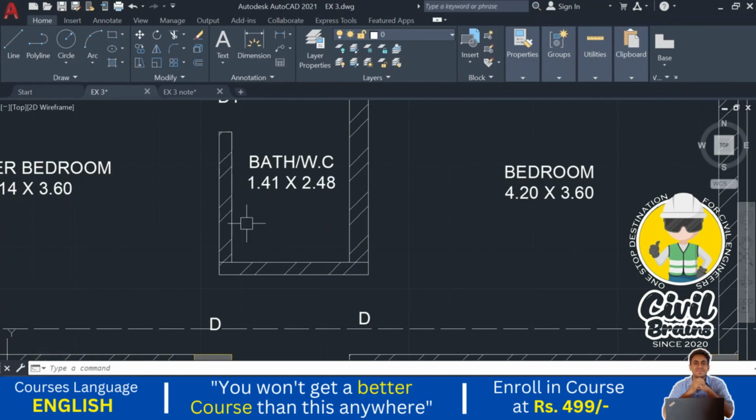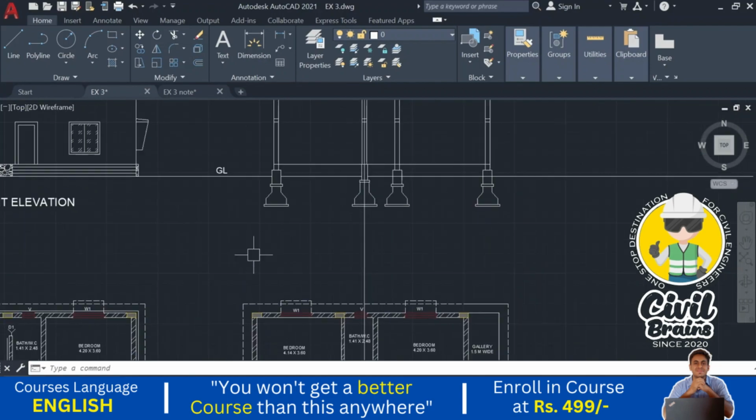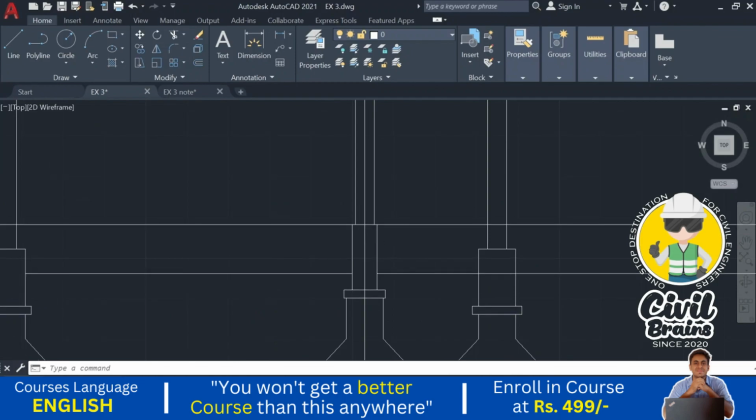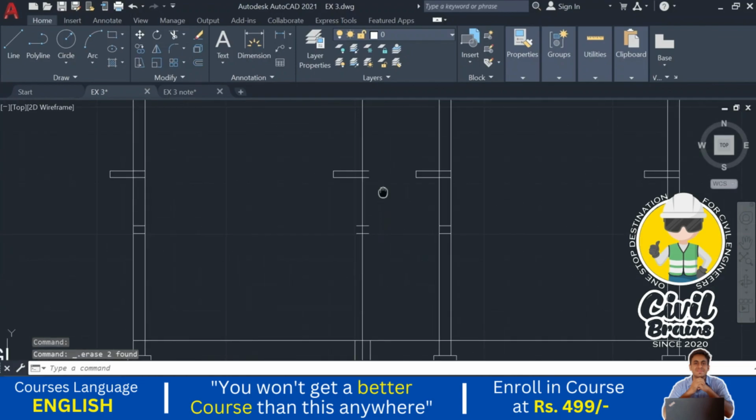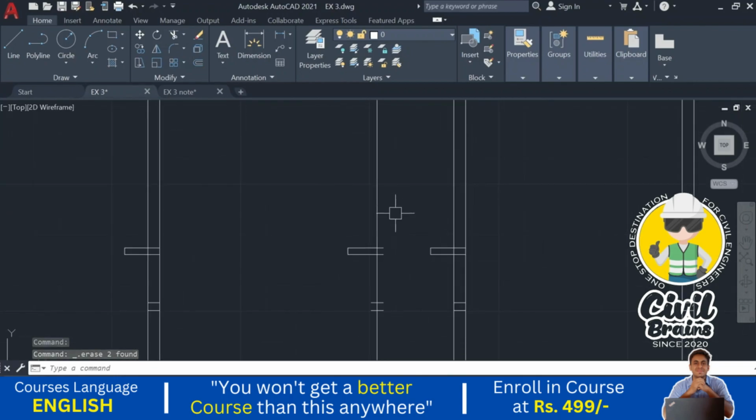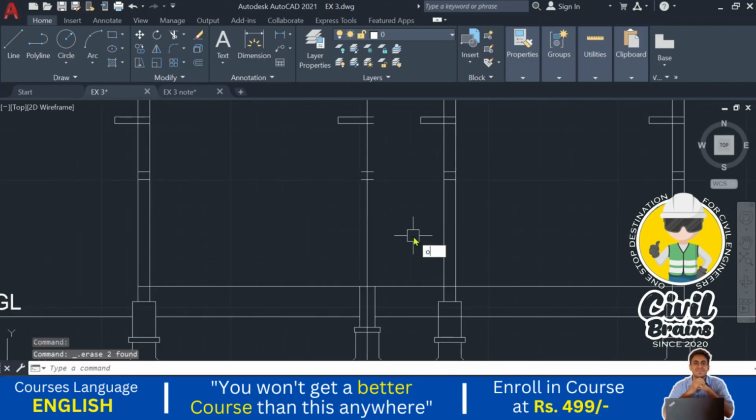So 0.15 we need to show. This wall thickness we need to show above the plinth 0.15. Just delete this wall. So offset 0.15 divided by 2, 0.075.